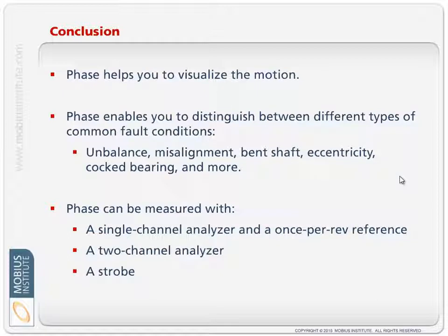That tells us about everything from unbalance to misalignment, looseness, resonance, all sorts of fault conditions that can be picked up thanks to phase. And we may even see, or we often do see, changes in the spectrum, but making sure that we've correlated correctly what those changes are to what the fault condition is, potentially means the machine failing or not, or getting unnecessary work done, that sort of thing.